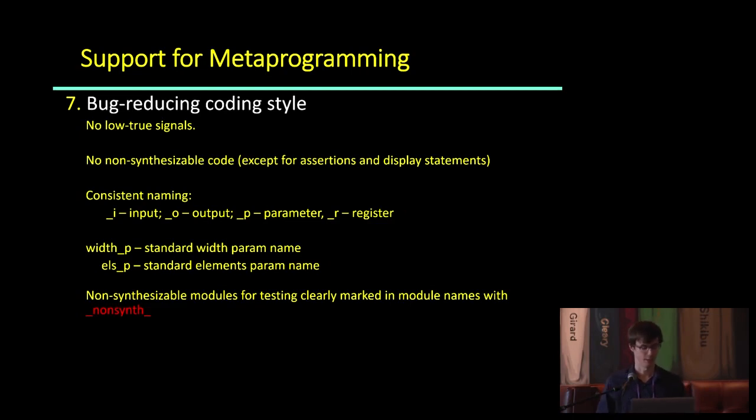And another key point of this is that non-synthesizable modules are clearly delineated. Non-synthesizable parts of modules are limited to assertions and display blocks, which means that your synthesis results are going to match your front-end results as much as possible.